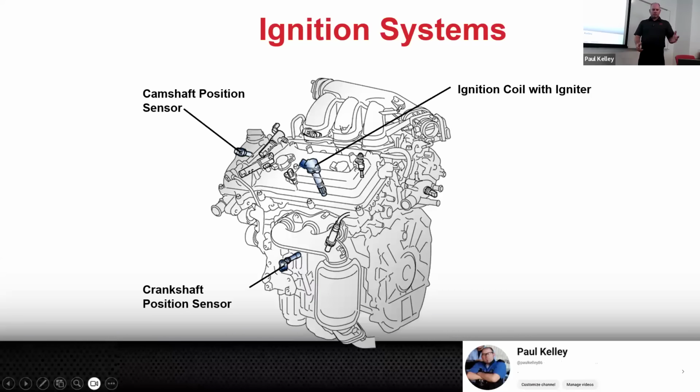But aside from swapping the coils, and that's quick, it's good, there's a few more things we could do. So if you look at this, one way to know without doing the swap and the retest drive and whatever, one way to know if this coil's working is we could see if it's outputting a spark. Anybody know how we would do that? There's a couple options. You familiar with this one? Take out the coil, just the coil, and you start it and see if it sparks.